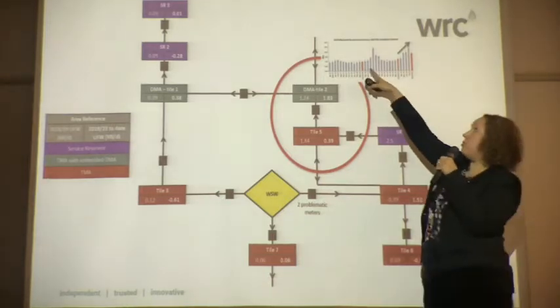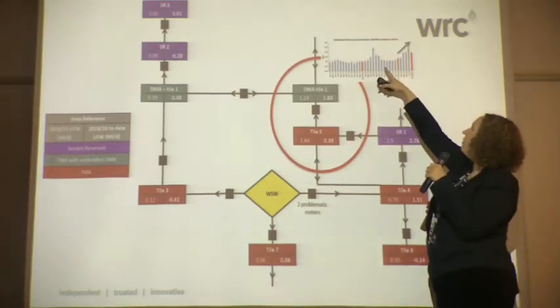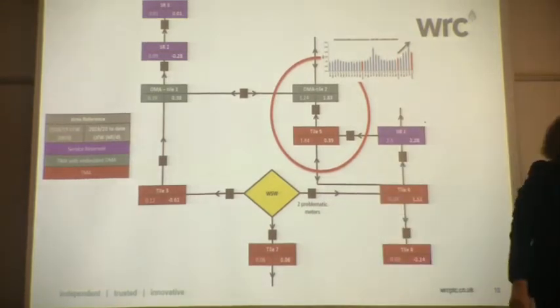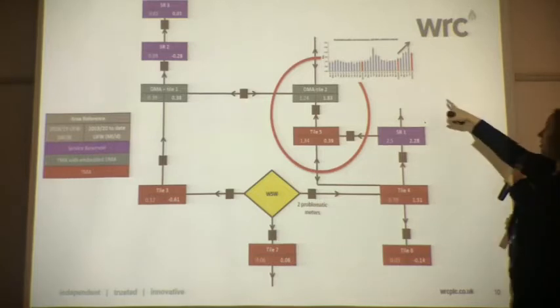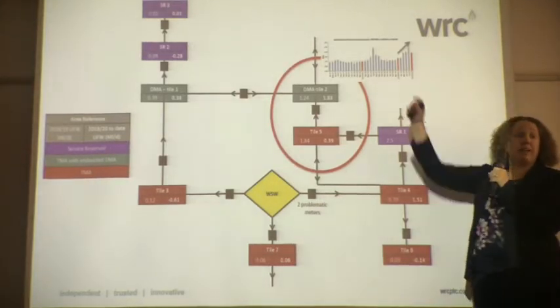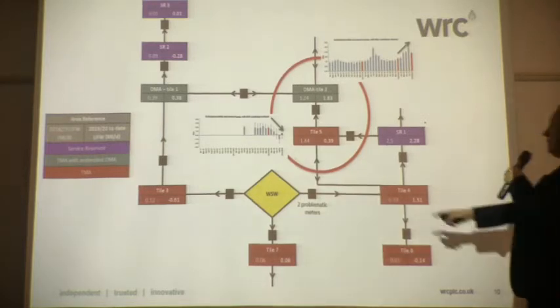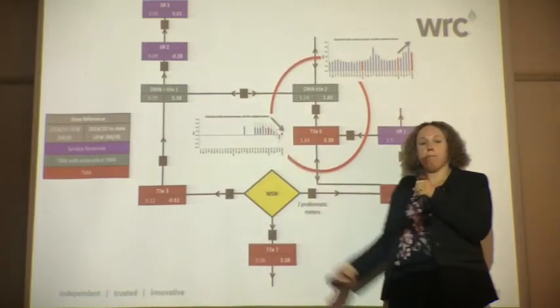We've got 2018's water use. Unsurprisingly, a big spike. It was hot, it was dry, everyone had their paddling pools out. It came back down during the winter, and then they saw a similar pattern in 2019. They went, 2019 was not as warm and beautifully sunny. So this company had been sending out resource to this DMA to look for leakage ever since they spotted this rising pattern, with no knowledge of what was going on in the upstream network. So we came along and produced an upstream balance for it. And unsurprisingly, in 2019 we saw a massive downward scale, dropping down to the negative.